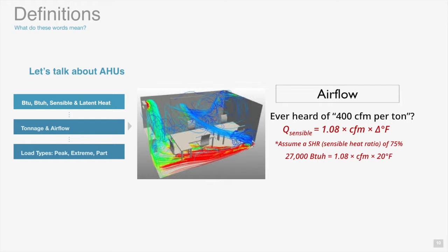That is a typical value. Then you move all of the numbers around and solve for CFM, and you end up getting somewhere close to 1227 CFM for this system. Now remember, it was a 3-ton system, so that's going to give us somewhere right around that 400 CFM per ton. It's kind of funny how that works out and how you are starting to see the trend of rounding happen.